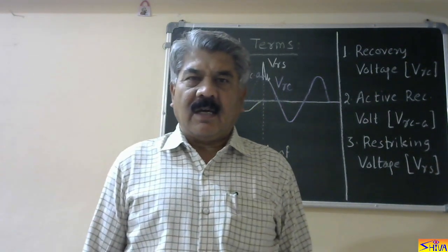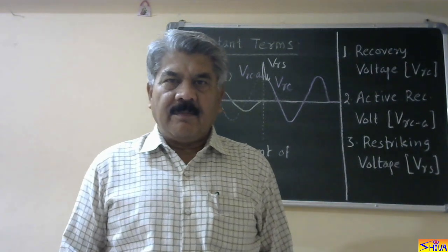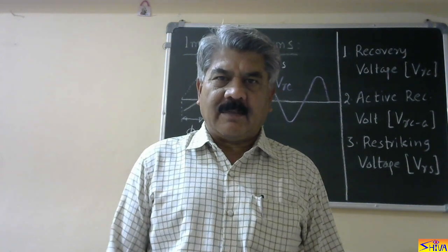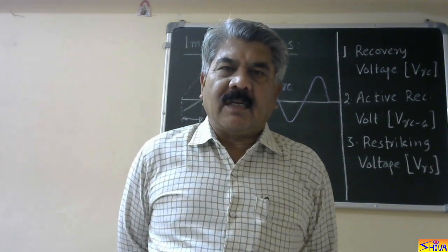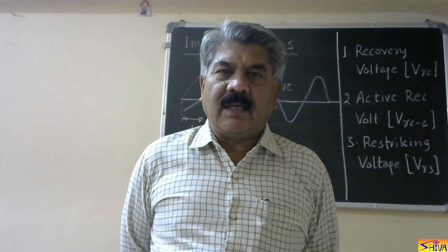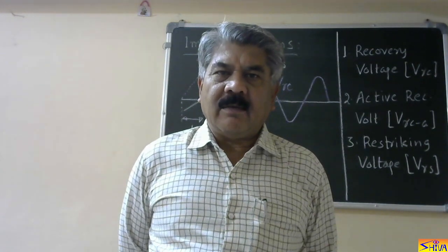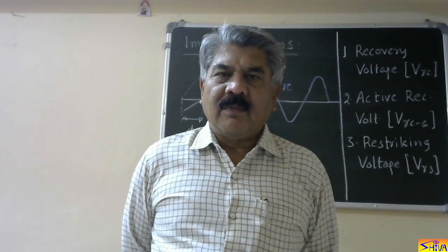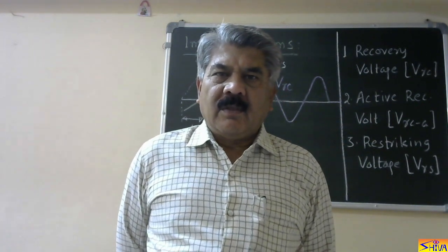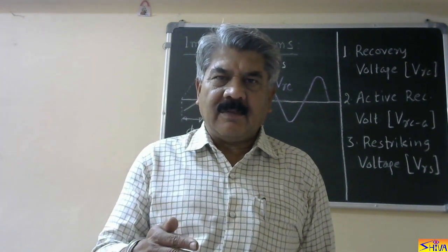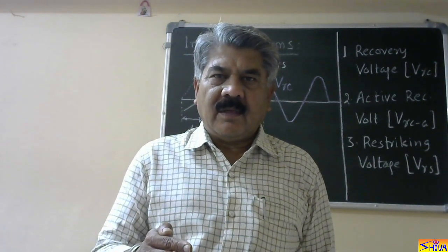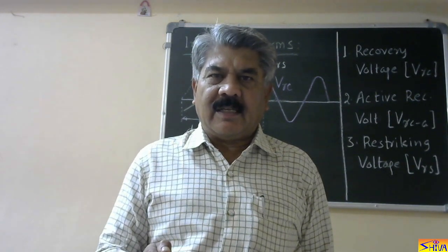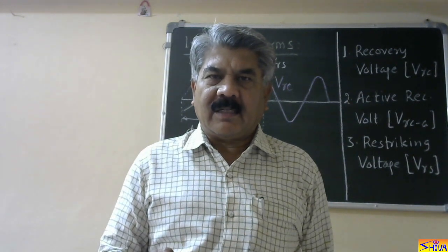So for this I will again go to the circuit breaker operating mechanism. As per definition, circuit breakers are nothing but two current carrying electrodes which are normally engaged but separate when their trip coil is energized, and trip coil is energized when relay operates. So the sequence is like this: fault occurs, relay detects the fault, it closes its contact. It closes its contact means the trip coil of the circuit breaker is energized. As soon as the trip coil is energized, the circuit breaker starts operating.